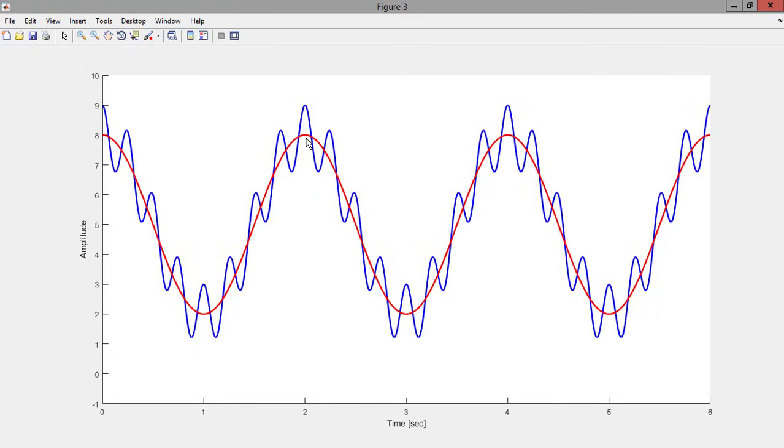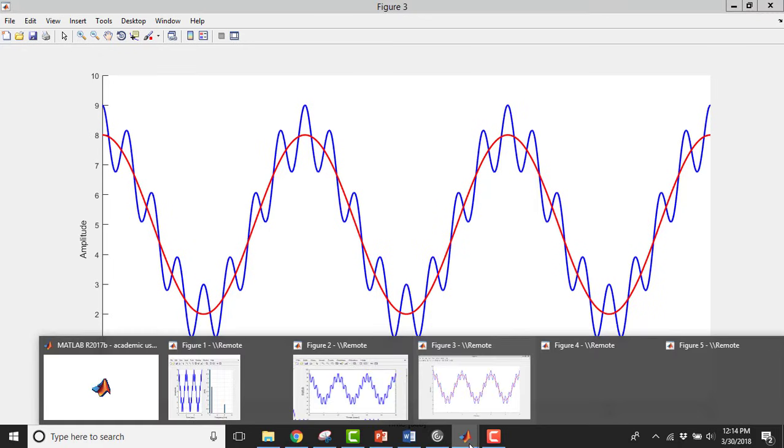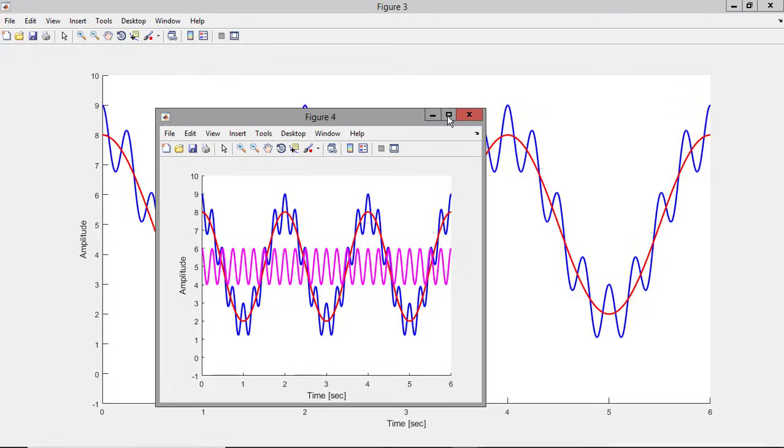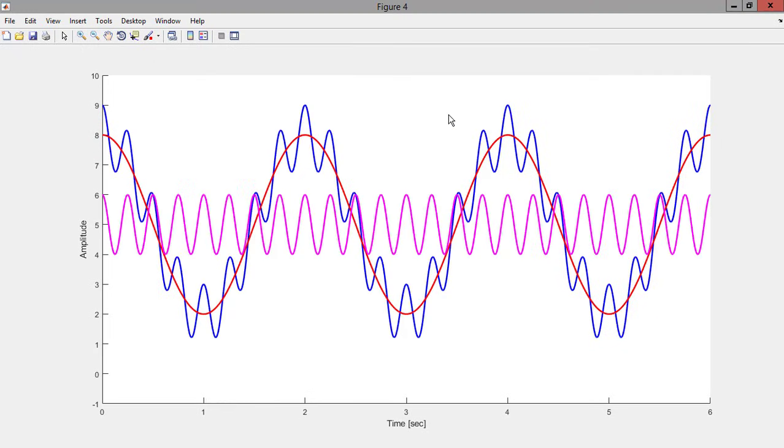Furthermore, it's clear that there is a DC offset to that component. So that 1/2 hertz sine wave or cosine wave is offset by an amplitude of 5. So that'll get me this red curve right through the middle of the curve on the exam. Now, on top of that, there is a higher frequency component riding on top of this 1/2 hertz fundamental frequency component. Now, this higher frequency component will be at 4 hertz. If you look, there are 1, 2, 3, 4 periods in a second, so that'll be 4 hertz.